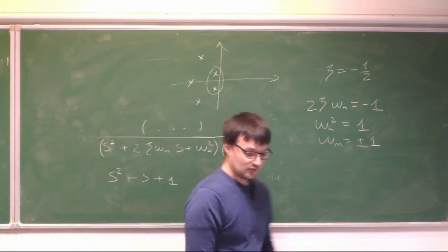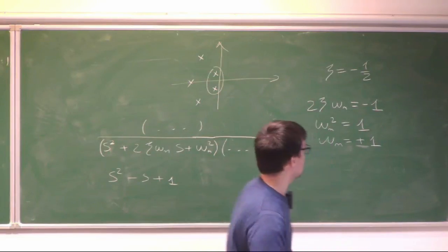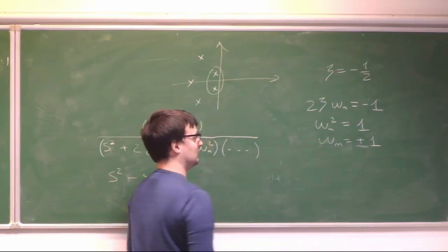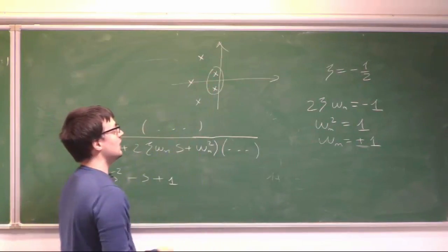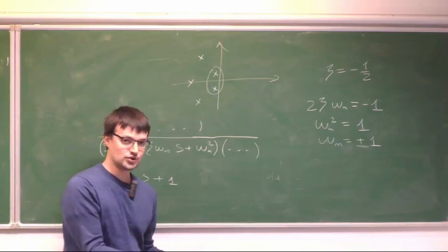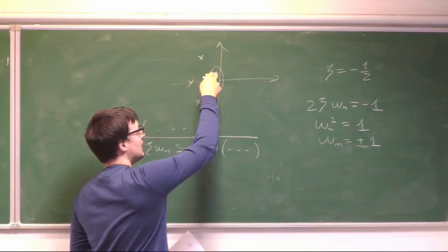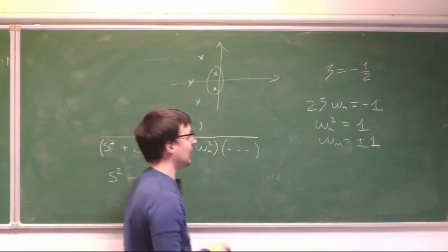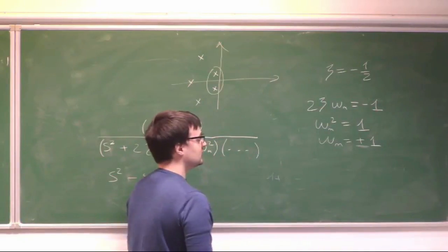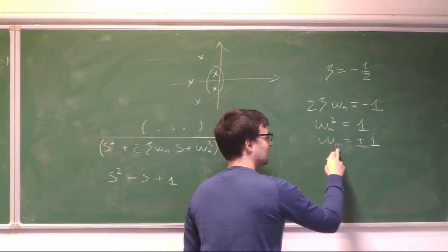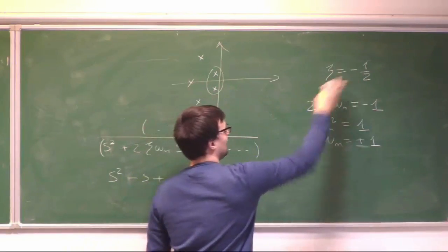So we said, if you look at the slide, that you want to select Ts between these two ranges where omega n is the natural frequency. What is the natural frequency? Well, here, since you have complex poles, you will have some oscillations. You will have a sinusoid. And since you are in the left-hand side of the plane, this oscillation will decay to 0, okay? So these two effects are explained by these two values, okay? So the natural frequency is the frequency of the sinusoid associated to this pole when the damping is equal to 0, okay?